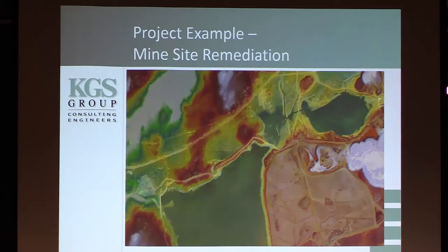This next site is a mine site remediation. Several LiDAR flights have been undertaken over various years of the site. It's a fairly large site, so traditional survey methods using GPS weren't really feasible to capture the whole site topography. So LiDAR was flown for multiple years, and digital elevation models were created. It's a mine closure site. So that was the original purpose of gathering the point cloud data, was to generate these digital elevation models.